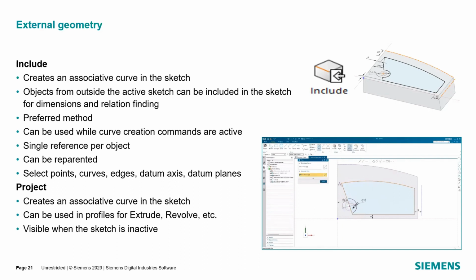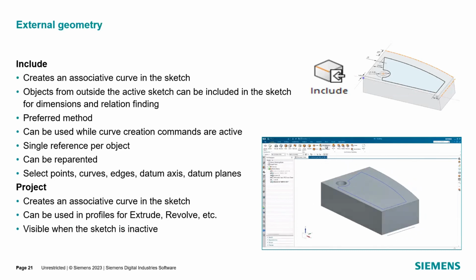Then as we make changes to that geometry exterior, that will still update and drive the sketch that we have. And so that just makes it very easy to put those external geometry drivers into the sketch environment. So we're not copying it, we're just referencing it. And so like the curve, now you see as we edit those or make changes, that information helps drive that particular edge.